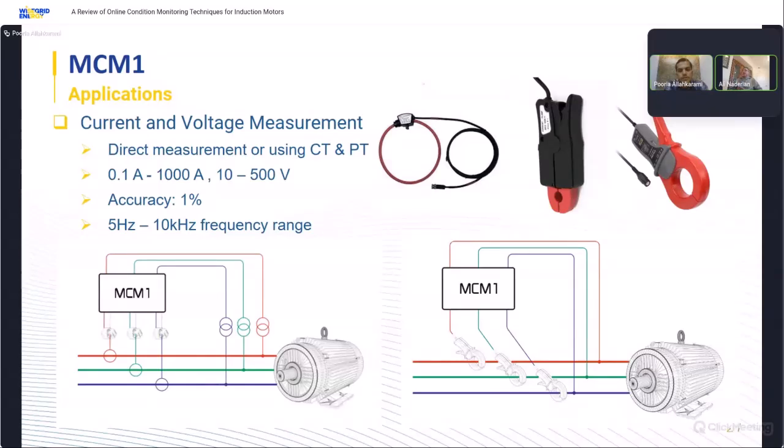And the good thing is it has both voltage and current inputs. For voltage, usually if you have access to the terminals of, let's say, the power panel, you can just clip or get a voltage from there directly. Yes, exactly. And you can measure from the output of the PT to have a power quality.